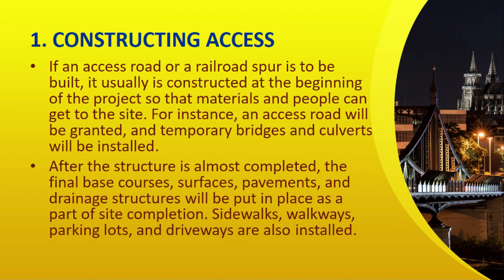After the structure is almost completed, the final base courses, surfaces, pavements, and drainage structures, such as culverts, will be put in place as a part of site completion. Sidewalks, walkways, parking lots, and driveways are also installed. The processes used in providing access are similar to those in other grading and paving operations.